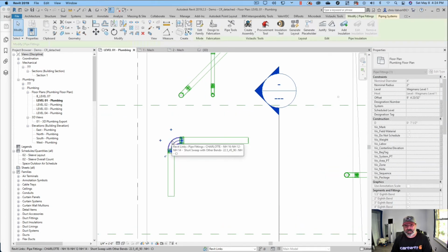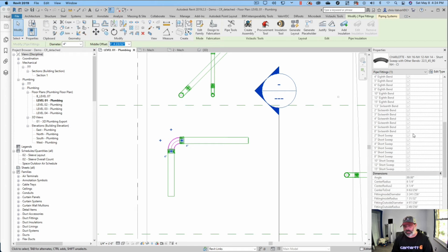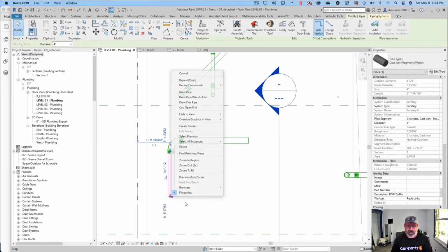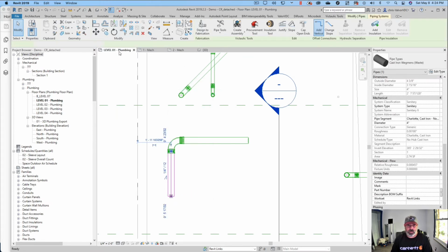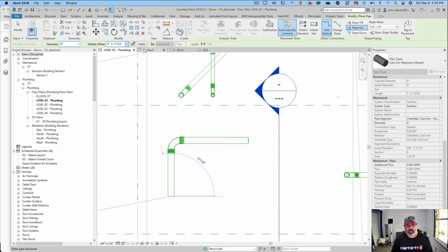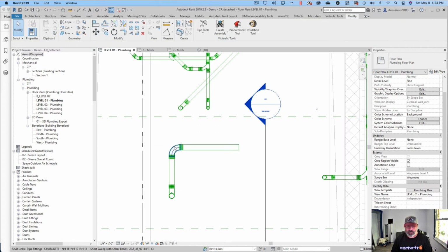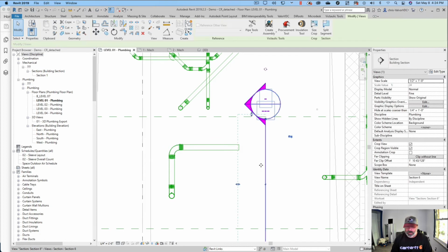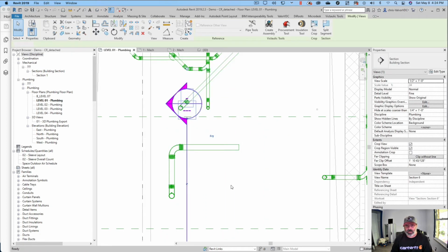And if I click on this elbow, this is a 90-degree elbow. And this is the same with fabrication fittings too. They're designed to flex. And what I mean by flexing is, if I click on this and I say you want to go 30 feet in the air, because on top of this Wegmans there's a building, and I hit apply twice, I come back over here, it's going to add this pipe. And if you look at this elbow, it's no longer 90, it's at 89.98, which meant that it had to fold a little bit to get there. And if I go over here and I click on this, you're going to see that this elbow flexes too. It's going to be like 89.14 or something.